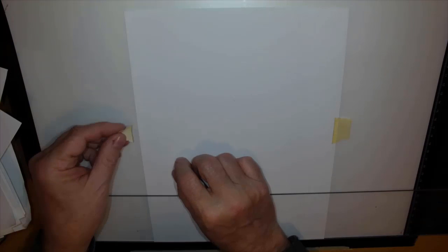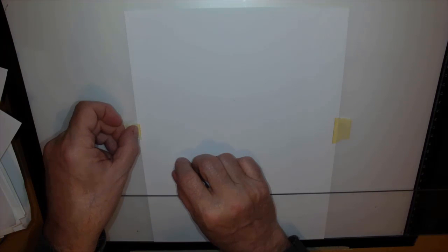with taping down our piece of paper, because the whole point of using our set square is to get perfect horizontal lines from top to bottom on our page. So that'll only maintain horizontal if our paper is actually taped down onto the work surface. So I'm going to use our T-square, and let me see if I can get this artwork as close as I can in the middle of our camera view here. And I'm going to try and line up the paper at the bottom here so that it lines up. Just going to overlap the tape just slightly, because we're going to need a 1/2 inch perimeter around here.